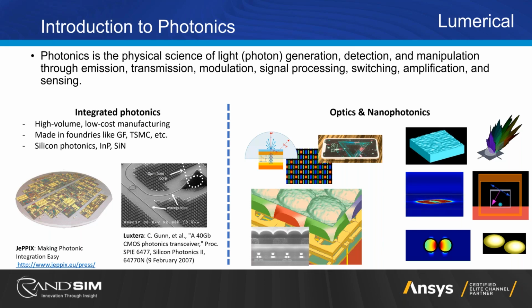On the other side, we have the more traditional optics and photonics space, which is more in line with Zemax and SPEOS. Here we can optimize diffractive gratings, we can do meta lenses, nano lenses, micro lenses, OLED display stacks. You may be wondering, why don't we just do that in Zemax? Zemax is a ray tracing tool that allows you to do this, but when you get into such small components, it's actually more helpful to use a system like Lumerical rather than just a ray tracing tool.